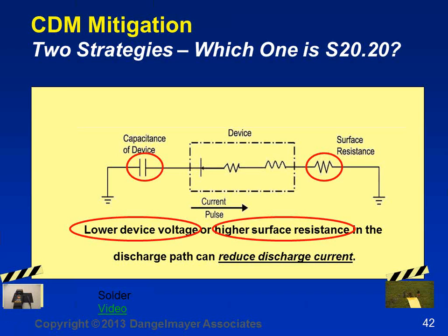For instance, tweezers. How many of you are using metal-tipped tweezers? That is a very high risk for a charged board event for components. If you substitute a pair of static dissipative tipped tweezers, that risk is greatly diminished, if not eliminated. Unfortunately, you can't just pick something off the shelf. There are many tweezers out there that claim they're ESD safe when they're not.